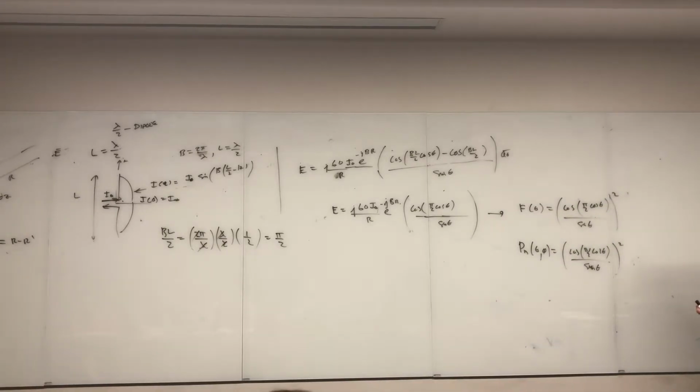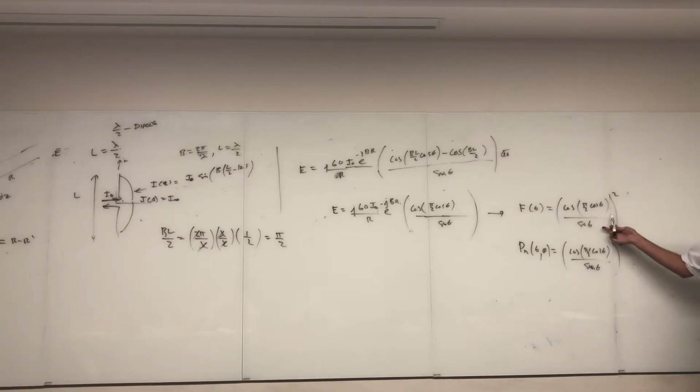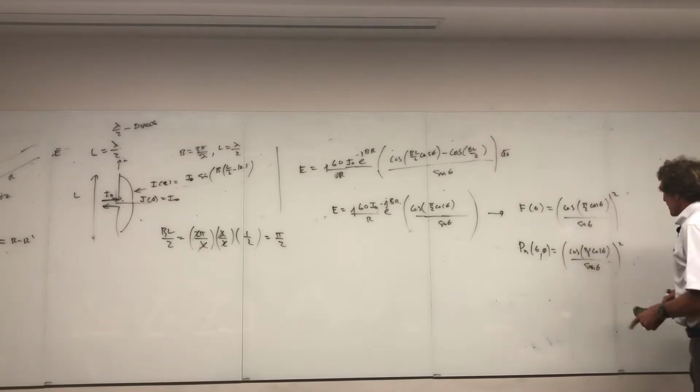Now, from this right here, we can plot the pattern, can't we, class? If we were to plot this, you're going to see it's almost the same as a short dipole, which is nice. Almost the same, but there's one super fact about this. Short dipoles have very low input impedance. This has a fairly high input impedance, which makes it preferred.